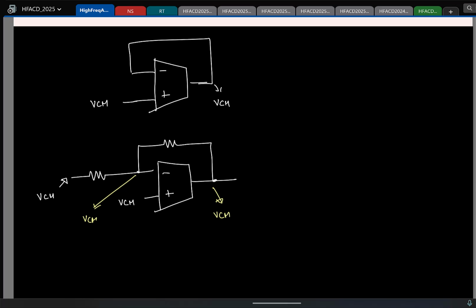Okay. So in general, the DC operating point or the DC bias points for a high gain op amp is set by the DC negative feedback around the op amp. So I'll say DC negative feedback sets the DC operating point.